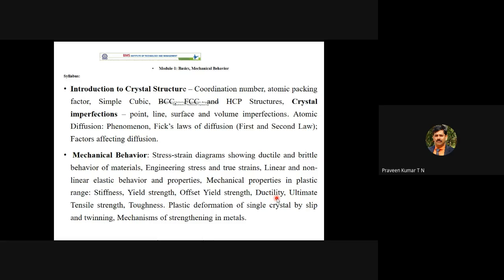So there is ductility. You have to find out the ductility. Imagine a steel rod is given. You have to find out what the ductility is. By conducting a tensile test, we can find out the ductility of the material. You have to remember, we can find out the ductility of any material by conducting a tensile test. There are formulas also available, but I am not talking about the formula now.